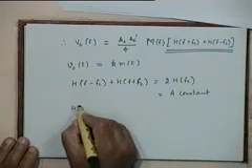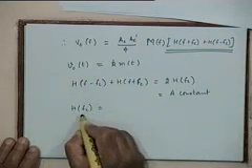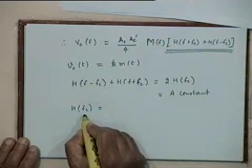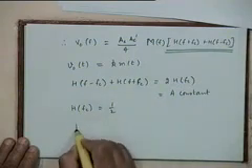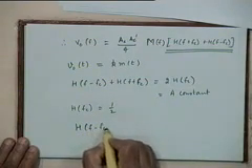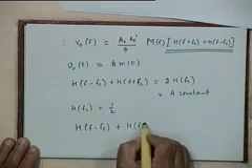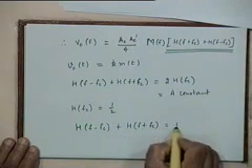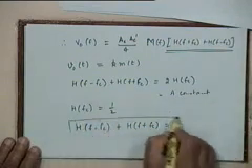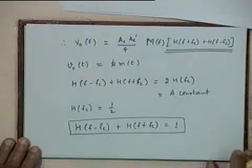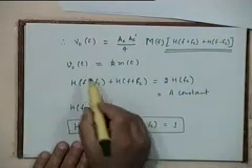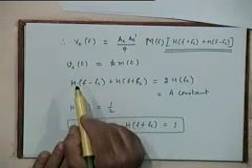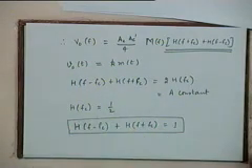And if I specifically choose the response of the filter transfer function at F equal to FC to be, let's say, equal to half, then this condition becomes equal to 1. Basically I'm choosing the constant to be equal to 1 arbitrarily, right? So the filter should be such that this condition is satisfied if you want your demodulated output through synchronous demodulation to actually be a replica of the message signal.